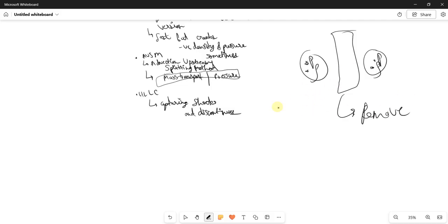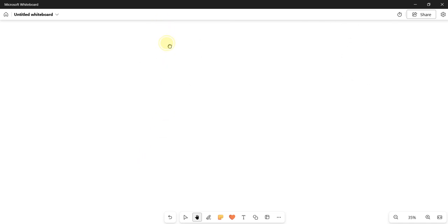That is what the Riemann problem is, and you have multiple solvers like the Roe scheme, the most used one, AUSM, and HLLC. You even have flux splitting, where you divide one flux into positive moving and negative moving flux. This is just to have a gist. There's nothing to know deeply.